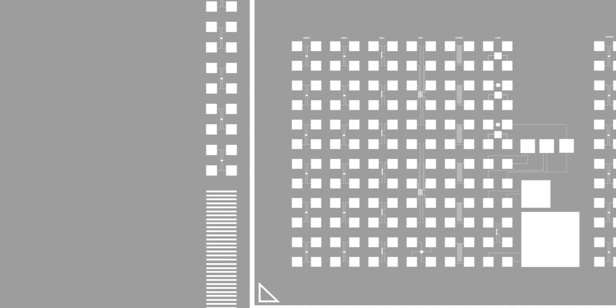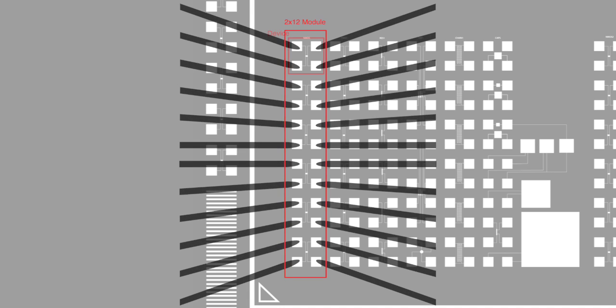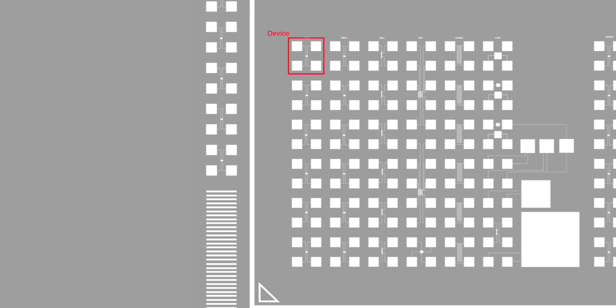On-wafer parametric testing uses specially constructed test structures defined across the wafer. These test structures are contacted by conductive needles of the probe card, which contact arrays of bond pads called modules. Modules consist of a variety of test devices tailored to the particular role requiring test.